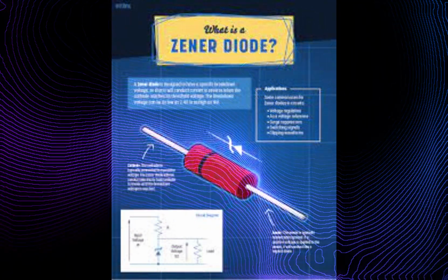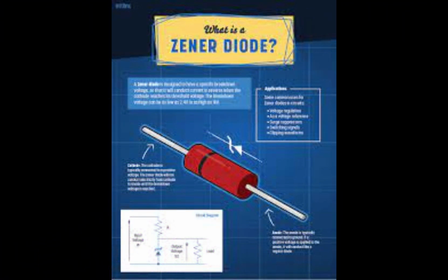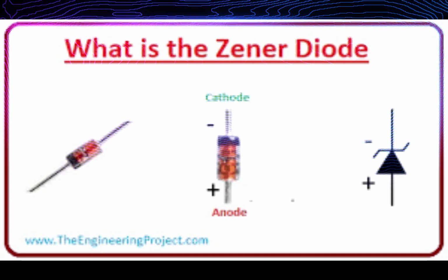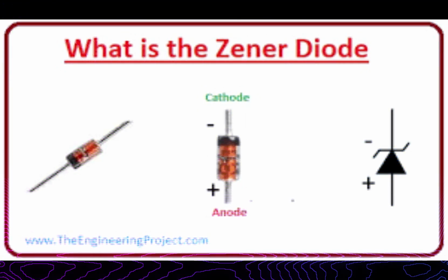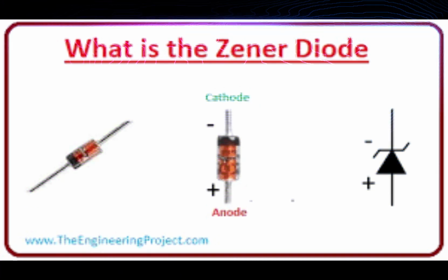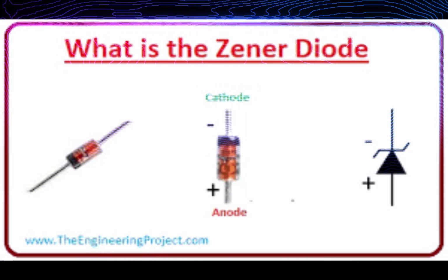Knowing these two effects will help you understand the functionality. First is the Zener effect, prevalent in voltages below 5.5 volts, and involves a tunneling effect to cause the breakdown. The second is the avalanche breakdown, or impact ionization, which occurs in voltages above 5.5 volts.